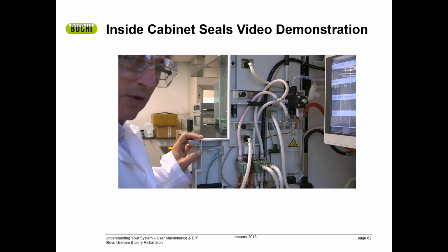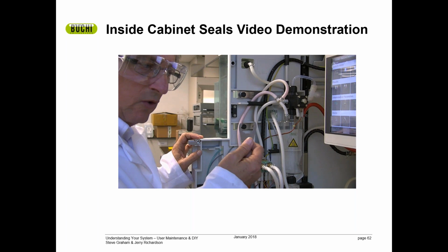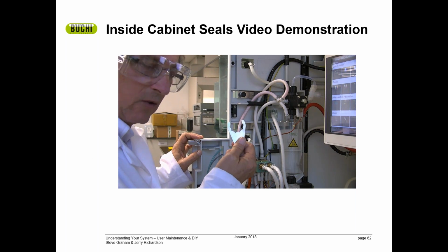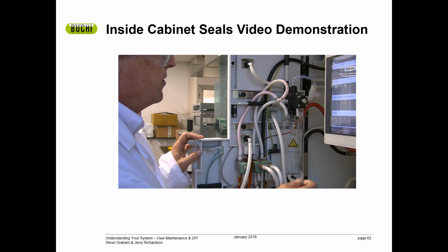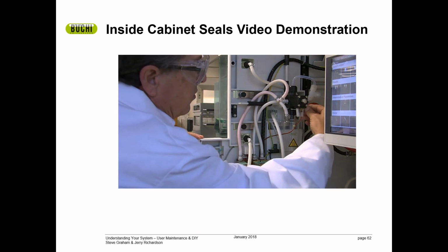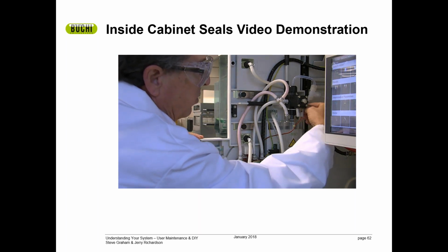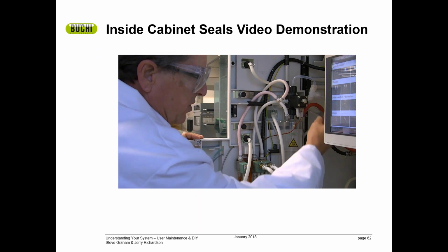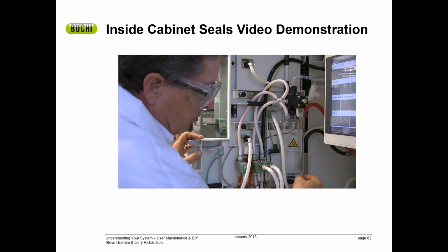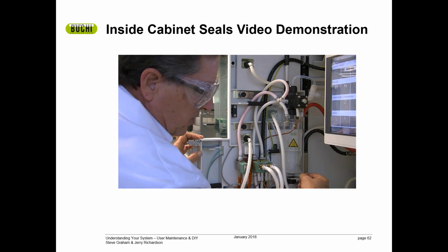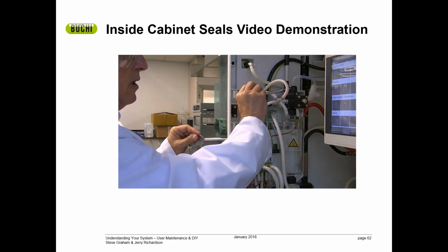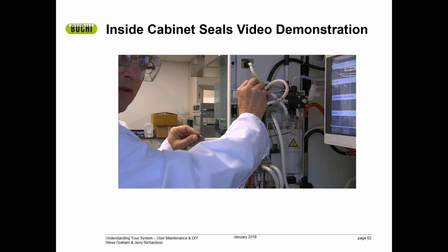These seals are addressed using your tool that we used on the front. This is the SVL22 tool. You simply put it on these black fittings on the top of the aspiration vessel and on the bottom of the aspiration vessel and at the very top on the aspiration valve.